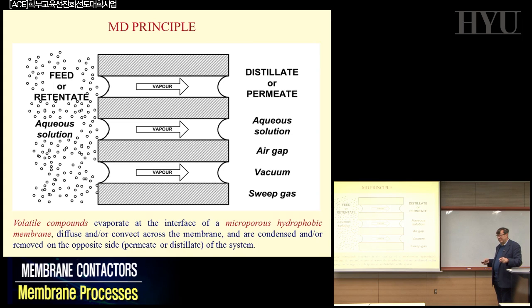If you have a different system, water and alcohol, for example, alcohol is a volatile. Or in wine, if you want to treat wine here, to concentrate it, you must be careful, because some of the volatiles, giving the aroma to your wine, etc., can go through. So in this case, you have to operate in a different way. Anyway, if this works, in principle, you can have molecules going across. You apply a small delta T, and they arrive on the other side. And here you can recondense your fresh water, because only water is going across.